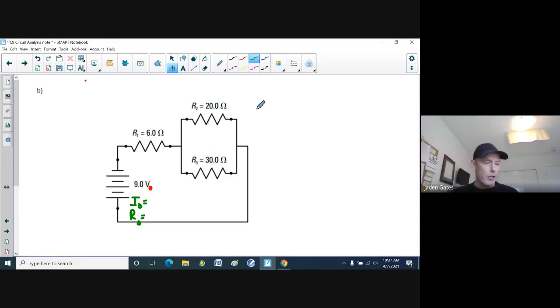Now, I have a parallel circuit inside a series. And so what I can do when I'm looking at this is, I guess the first thing is I can find R23, combining those 2 circuits to find out what my resistance would be if I combine them, because then I'll be able to figure out RO. All right, so again, because it's in parallel, I got 1 over 20, plus 1 over 30. And then I have to take it to the power of -1.